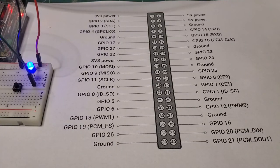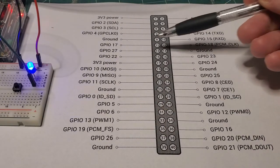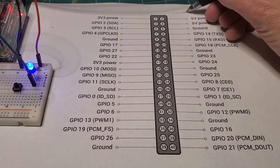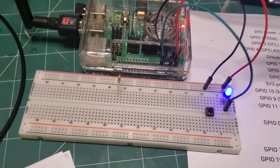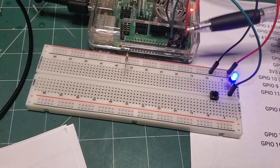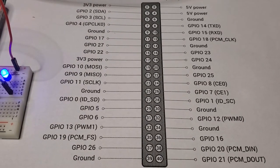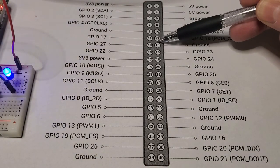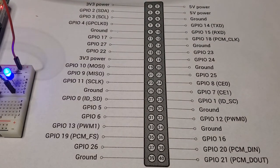Okay, so let's spend a bit of time going over the various GPIO pins that exist on the Pi. Here's the standard 40-pin header that's been used in the Pi for some time, and this is the outside of the Pi here. So pin 1 starts on the inside here. So it goes pin 1, 2, 3, 4, and so on. Now, interestingly, the GPIO numbers themselves don't correspond in any way to the header pin numbers. So you can see here, GPIO 18 is pin 12, and there's no real relationship between the GPIO number and the actual header pin number.